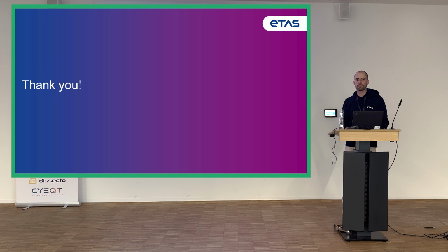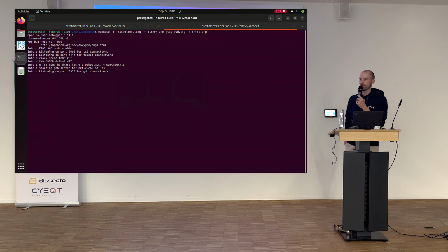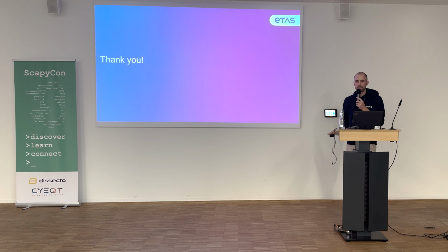Do you happen to know what they did in revision 3 to protect against potential attacks? Yeah, so I don't fully remember it, but they basically changed it so that it's locked by default. This register has a default value that causes it to be locked, and if you want to unlock it, in software during boot, you have to write a specific other value to this register to make it unlocked. And again, I'm not entirely sure, but I think this is what they did.